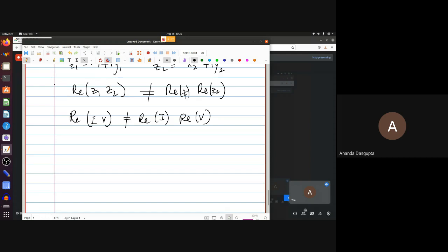Whenever you have nonlinear operations, you can't do this. And that is one of the reasons why small signal AC models are so important. Because we have sinusoidal signals coming in and going out, you will actually use complex currents and voltages a lot, even in nonlinear circuits. But you are really not going to use it in a fully nonlinear circuit, because there this calculation is completely wrong.